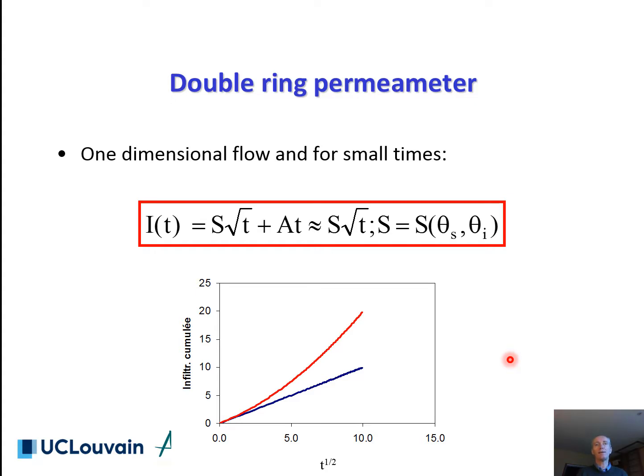It is therefore expected that we can easily make an error of nearly 30% when assimilating the steady-state infiltration rate A to Ks. Yet, this error is still often acceptable in practical applications, given that the Ks, the hydraulic conductivity at saturation, may vary by different orders of magnitude within the field.